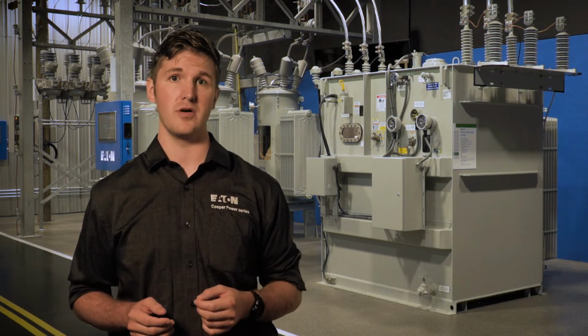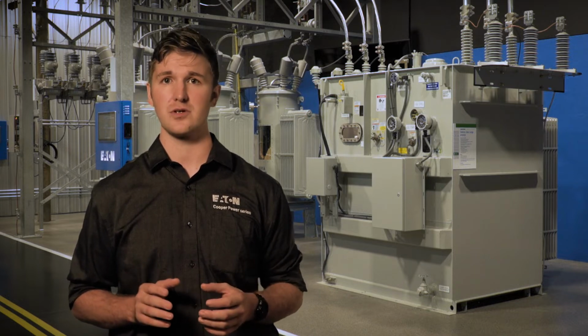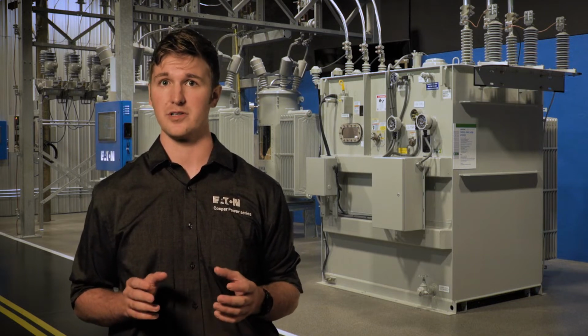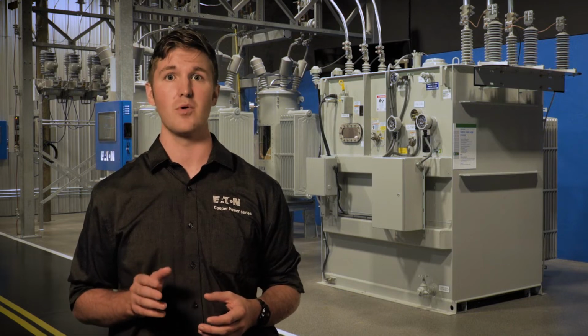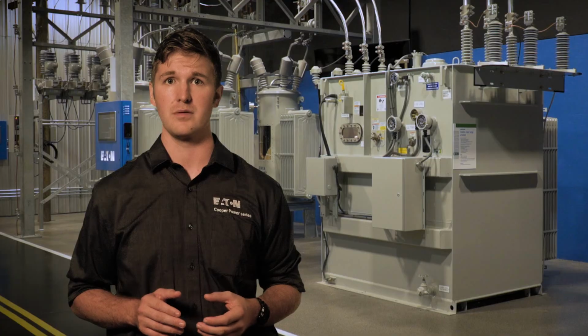Medium voltage distribution transformers deliver a significant amount of power from the grid connection to the secondary with high amps on the low voltage side. This extreme amount of power is throttled only by the electrical impedance of the transformer during a fault condition. However, it is still more than enough to devastate equipment or personnel if an arc flash event were to occur.